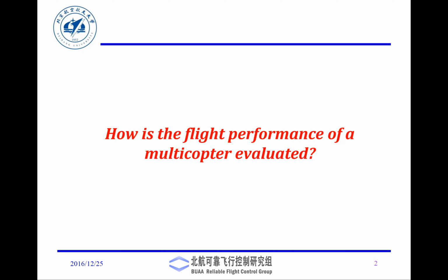Another important concept that we need to take into account is that the thrust generated by the prop is approximately proportional to speed. I will give you an expression. It also depends upon the diameter and the chord length. But in general, once you have decided the dimensions of a particular prop, you would notice that the thrust generated by the prop is proportional to the square of the speed. Speed is something that we will control using the ESCs.